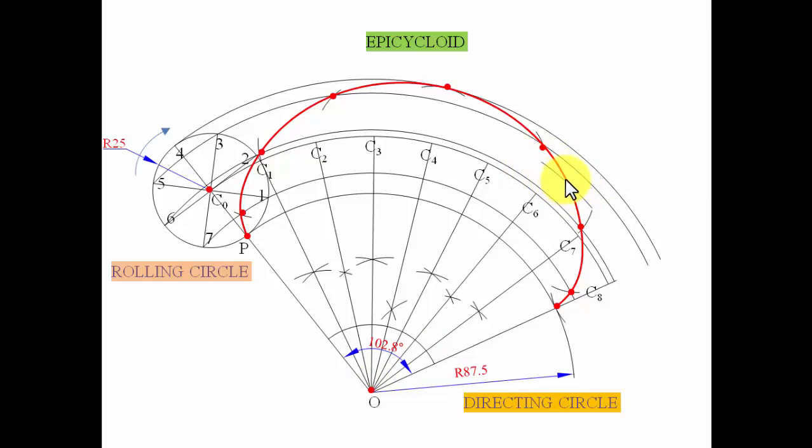This particular arc is intersecting this epicycloid over here, and hence you can say that this point is at a distance of 125 from this O. Let's say this point is named Q. With Q as the center, and somewhere along this center arc, we are going to put an arc yet again, with a radius of 25 millimeters, small r. Small r corresponds to the rolling circle radius. So with Q as center, I'll put an arc over here, something like this. So this point I'm talking about.